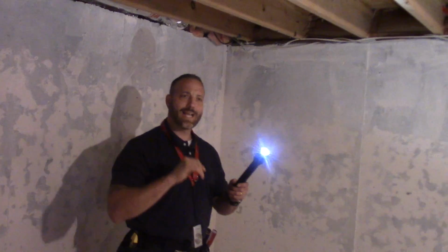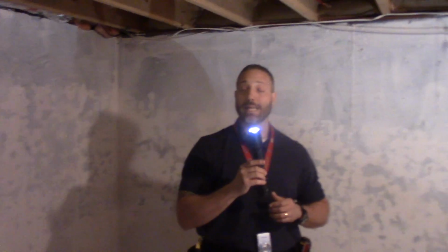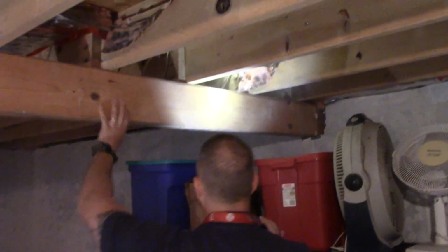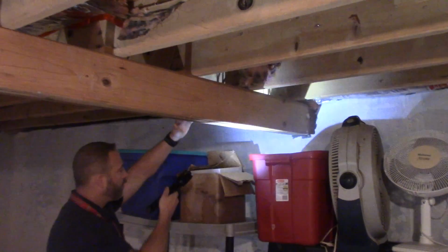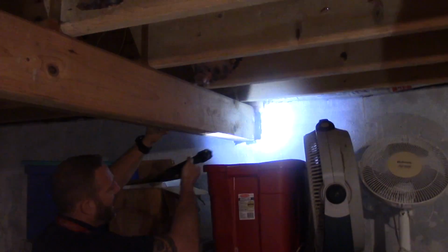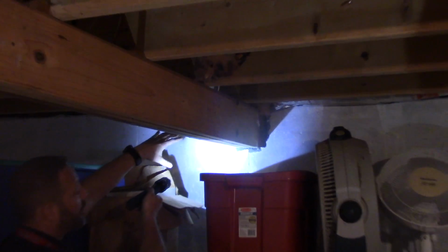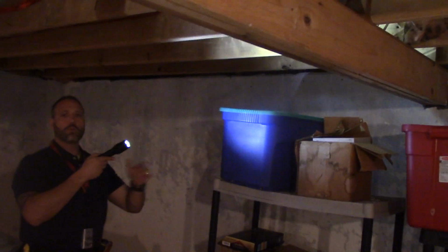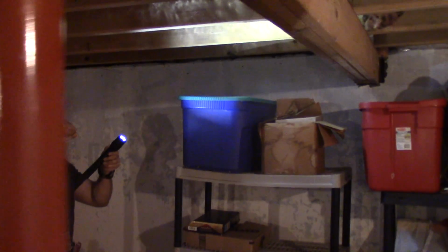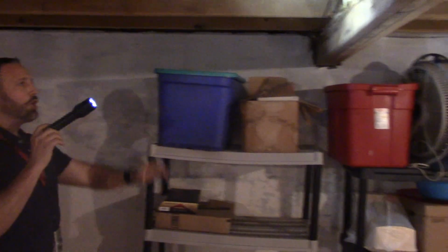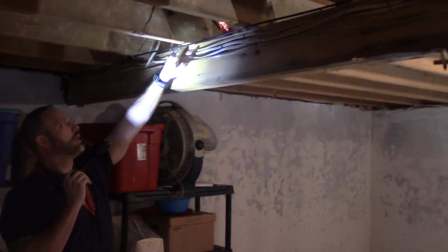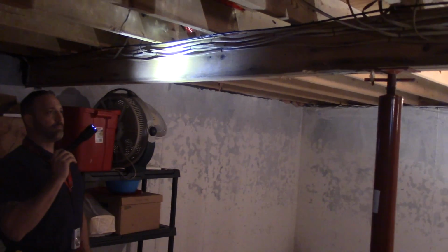Now, one of the next elements we have is our main beam and our supporting joists. So here's our main beam. It is actually built up with wood. We can see we have a pocket in the foundation. That is the supporting structure for our main beam, which carries the load to the footer. Now, we're going to be looking at this main beam from afar, and one thing we want to see is, is there any bow in this main beam, which I'm not seeing any bow. We want to make sure that the joists are overlapping over the main beam.